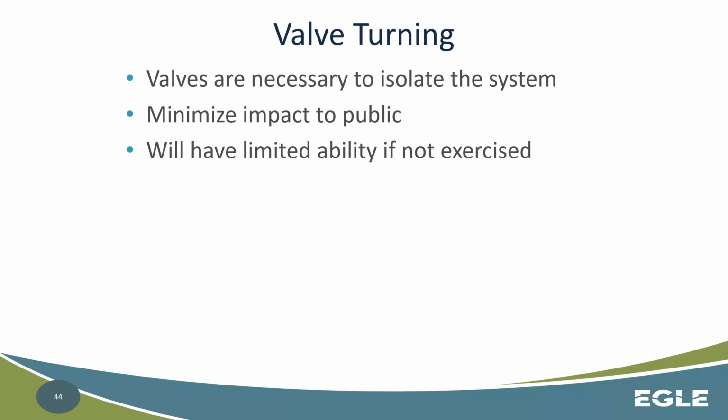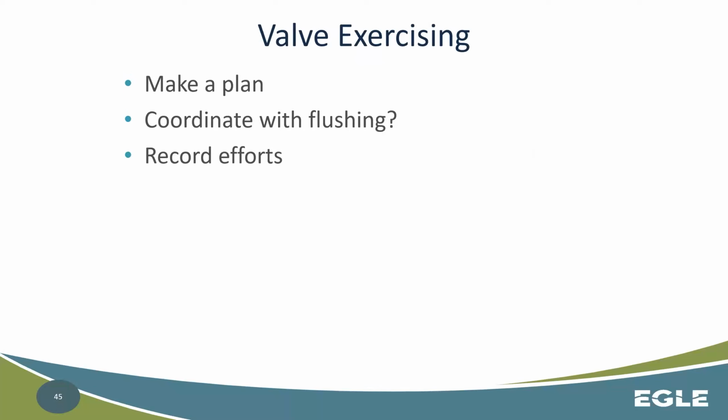There are valves in the system that are more and less prone to these issues. Resilient wedge valves are typically less prone to issues of closure from scaling and other things like that. Butterfly valves, on the other hand, are very prone to scale buildup and not being able to get a proper seal on the valve.